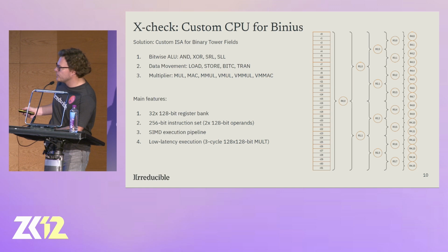So we are able to perform large multiplications together with load-store operations in 3 clock cycles, which also helps the compiler work better. On the right-hand side is the register bank, and what's interesting here, we enable several ways to address registers. Obviously, you can access a single register from the compiler standpoint, but you can also address an entire range of registers and also at different offsets.